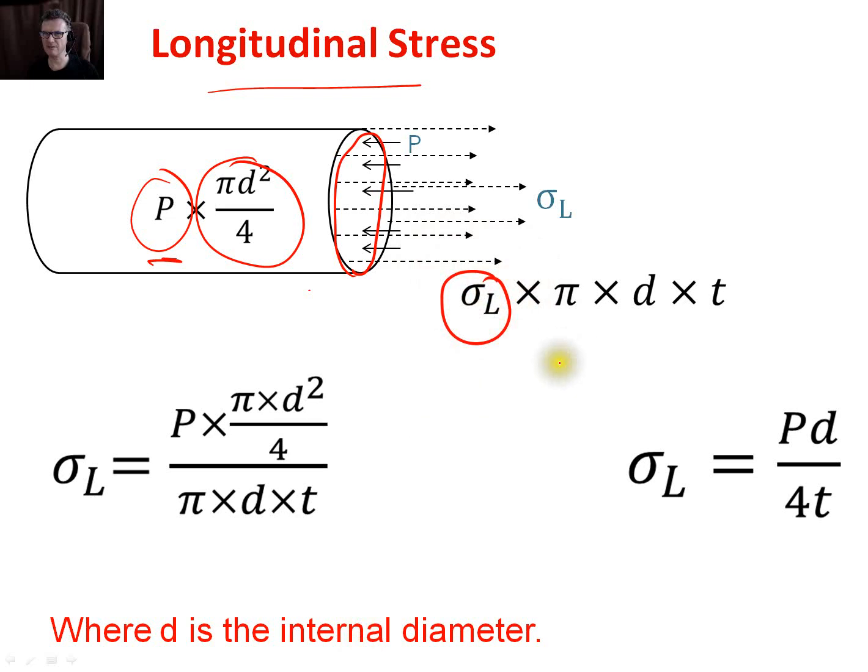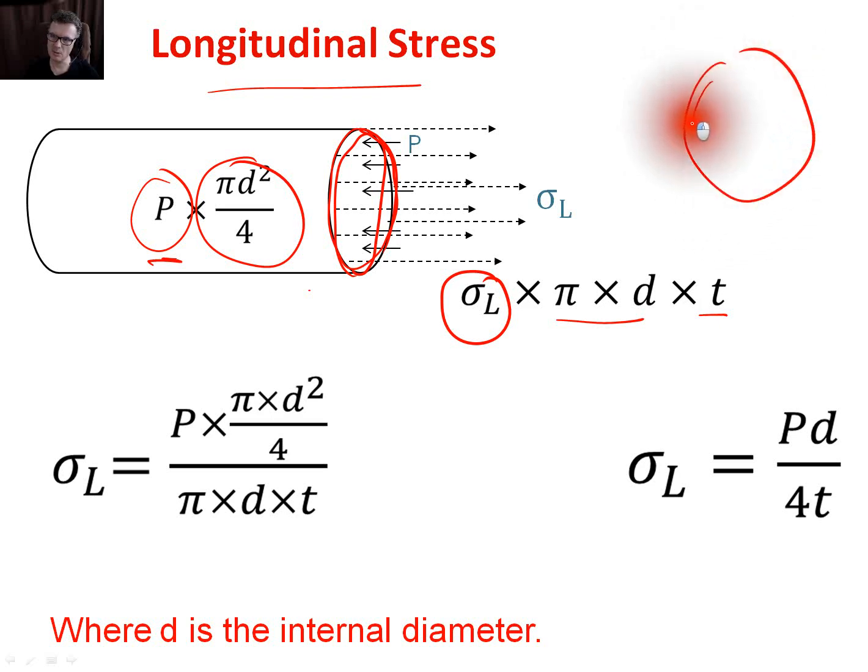What is the area of that wall that's fighting this gas, trying to push it apart? Well, that will be the length times its thickness. So what we're doing is we're imagining that we can model the area for a very thin hoop.